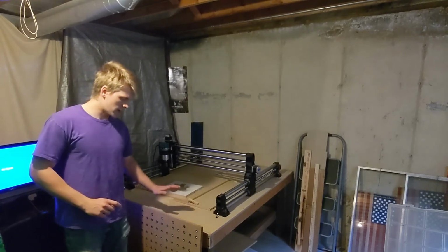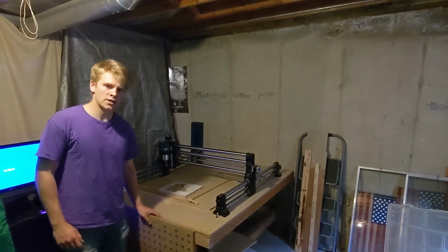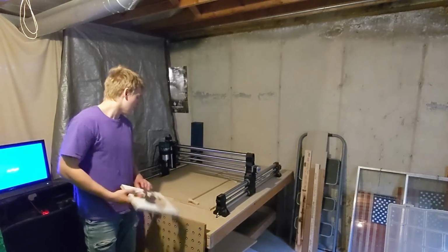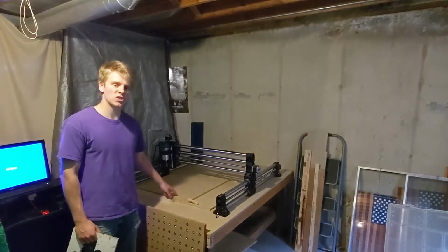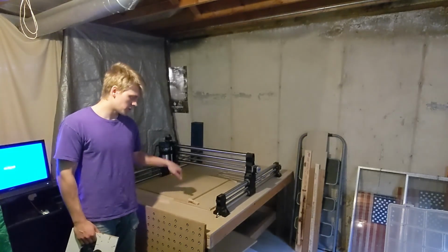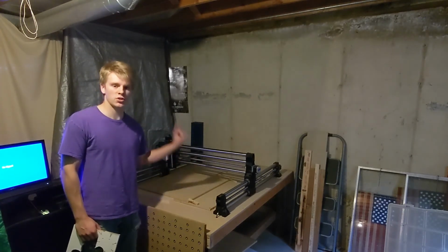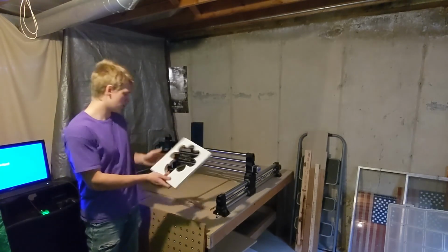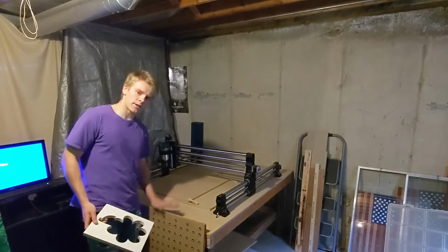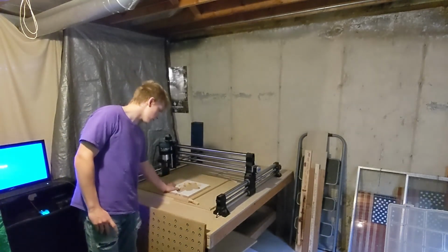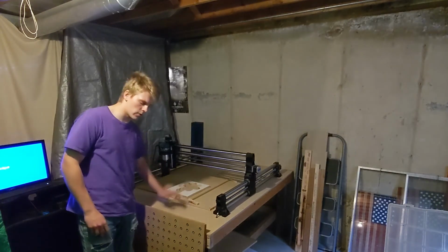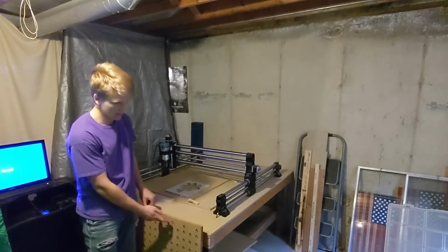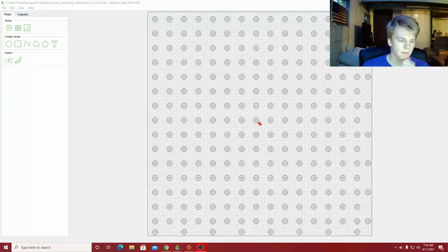Alrighty, so before I screw this spoil board down and surface it, I'm going to make a smaller one. This smaller one is 23 7/8 by 24 7/8. I'm just going to drill 5/16 holes that should line up with this one. So if I ever want to do a profile cutout, I lay this on top of this spoil board, and then it'll eat into this board, because I would like this to stay as nice as possible because it has these T-nuts in there. So that's the plan.